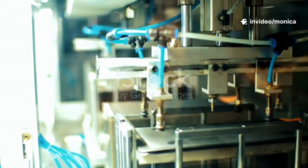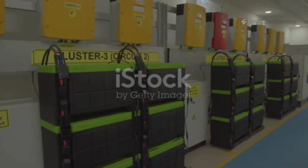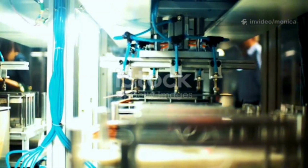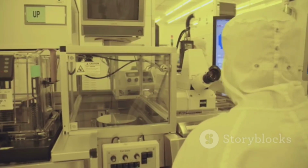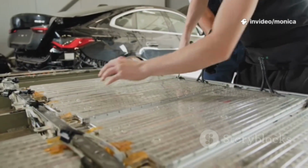In-process quality checks: continuous monitoring during production, including visual inspection and dimension checks. Visual inspection means checking for defects in electrodes, separators, and cell casing. And the dimension check ensures components meet size and thickness specifications.